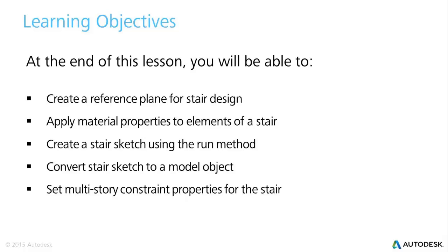First, we create a reference plane to help with stair design and layout. Next, we apply material properties to elements of a stair. Next, we sketch a stair path using the run method. And then we convert the stair sketch to a 3D model object. And then last, we set the multi-story constraint properties for the stair so it can actually transcend multiple floor levels. With that, let's get started.